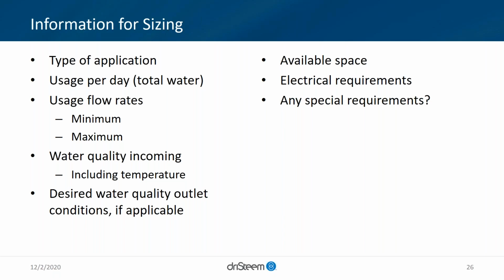What's the total usage per day? And as we look at that, a lot of the ROs, including our own, have how many gallons per day it can produce, as well as what its flow rate per day. We want to make sure we size accordingly so that you can have some maintenance time and you have some safety factor along with what that total usage is. What the usage flow rates are.